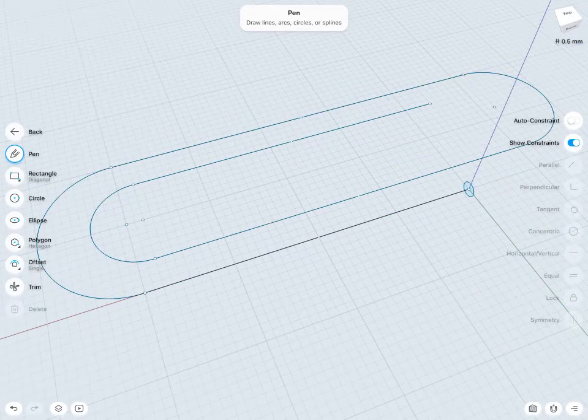Every sweep we design will consist of a profile and a path, just like we're seeing here. Again, the profile can be essentially any closed shape you may want, and the path can be of any particular complexity you may need. So using the sweep command, you can come up with some very, very nice and complex designs.